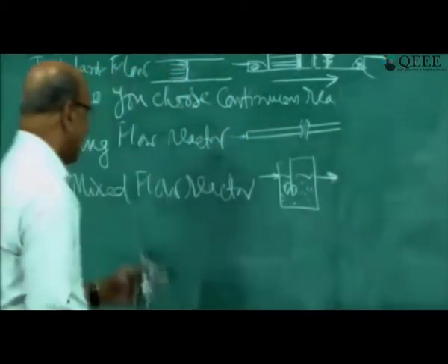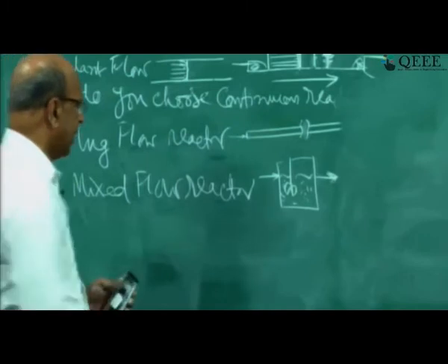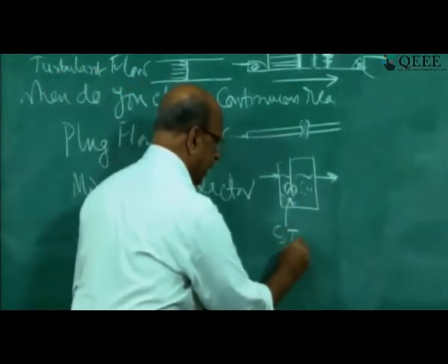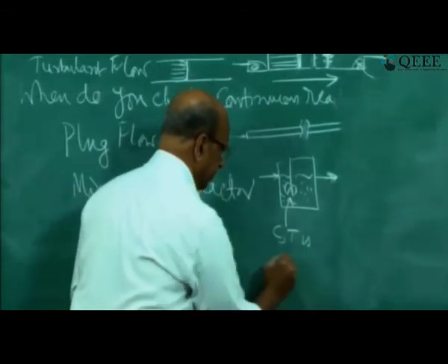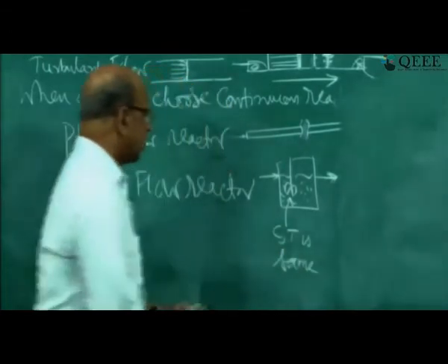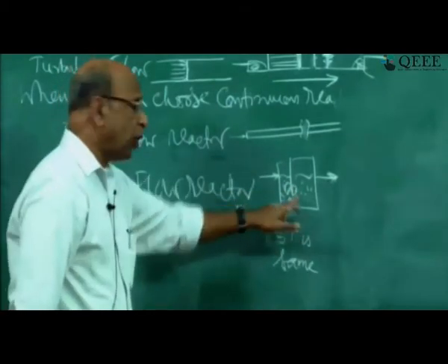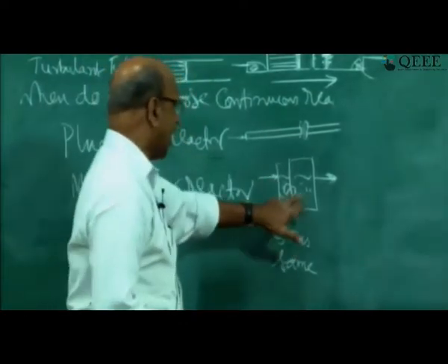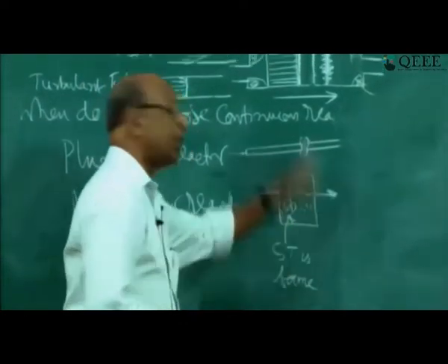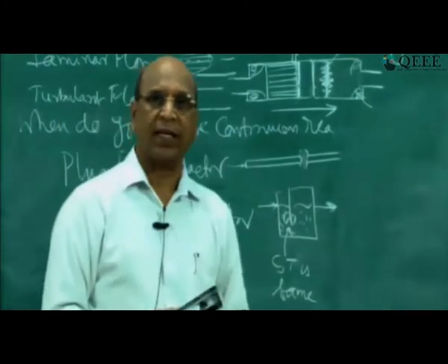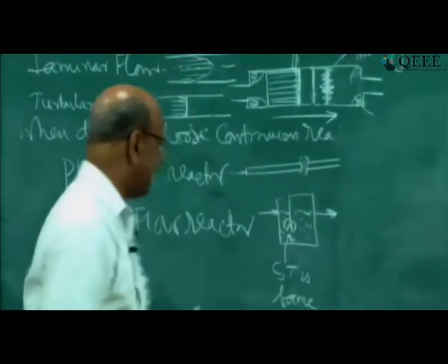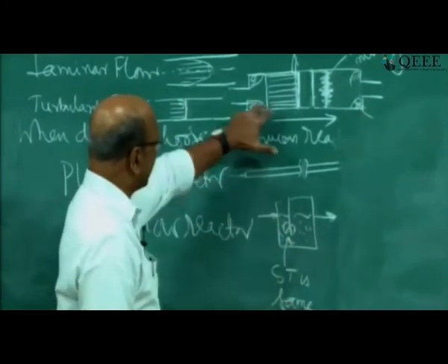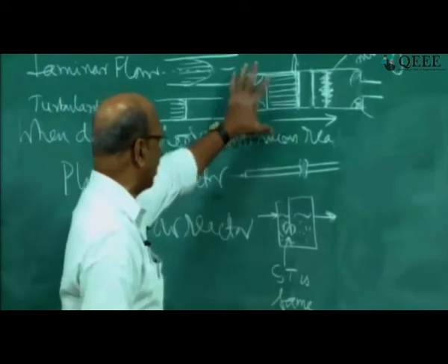And here the ideal mixed flow is that at every point concentration and temperature are the same. This is because of perfect mixing. So you should have perfect mixing in the reactor so that the temperature and concentration are uniform throughout the reactor. Okay. So this is very easy to understand, but I think plug flow is slightly difficult to understand. That's why it took more time.